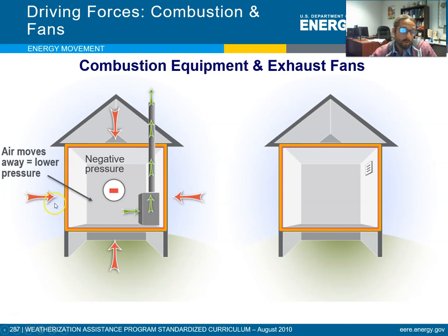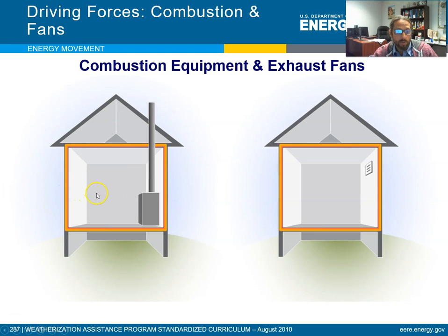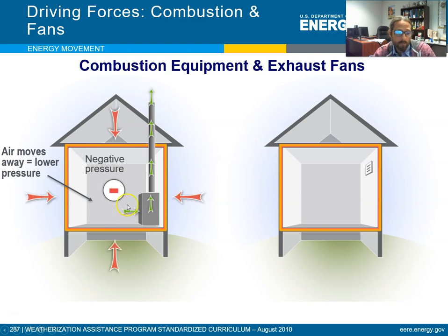Okay. So to sort of wrap it up, we'll go back to the beginning, right? So when you start a furnace, you're pulling oxygenated air from inside and you're dumping it outside. When you do that, you depressurize, you move air away, so you create this low pressure zone. So you depressurize the whole house or whole building, and then that's actually going to pull cold air in from the outside. And again, there's ways to go around this through direct combustion, but we'll talk about that later.